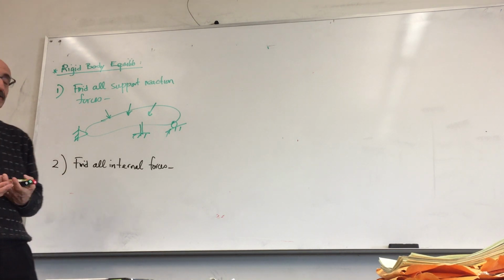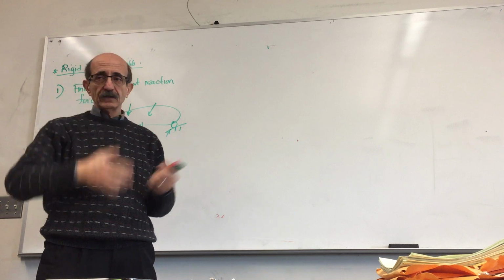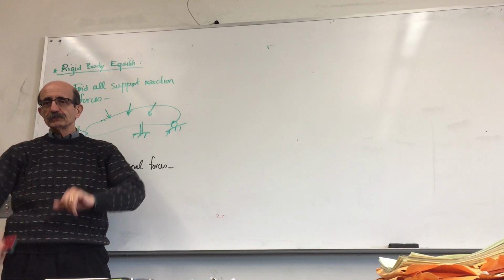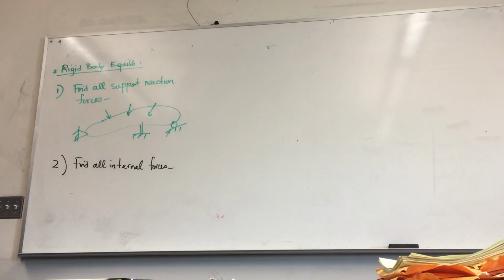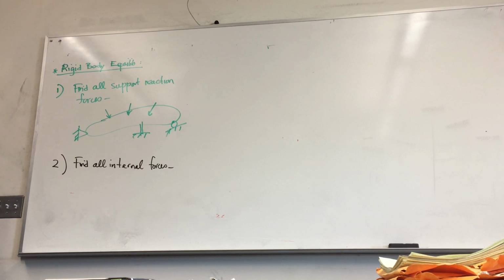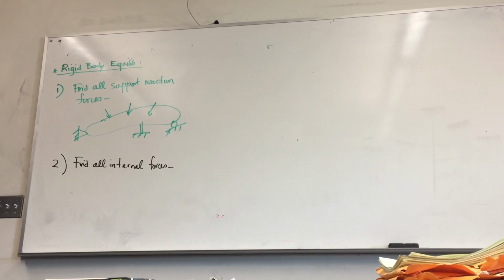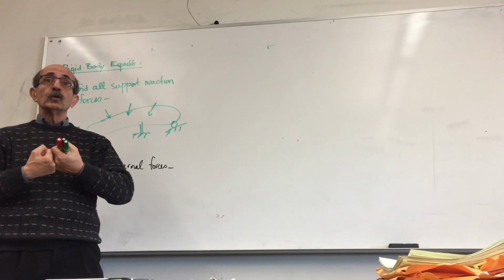Every structure is made of pieces, components, that are put together, connected together to make that a structure. A chair that I always refer to is the easiest, good example. Made of that seat, the legs, that platform, they're all connected together through some bolts or welded joints and whatnot to make that a structure to hold the weight of your body, right? That is a structure. In order to design that, besides the fact that we need to know what is the applied load and what forces from the ground act on that chair, we also need to find the right connecting devices, whether it's a bolt or a welding, to connect these pieces. So we need to know what forces those connections will be subjected to.